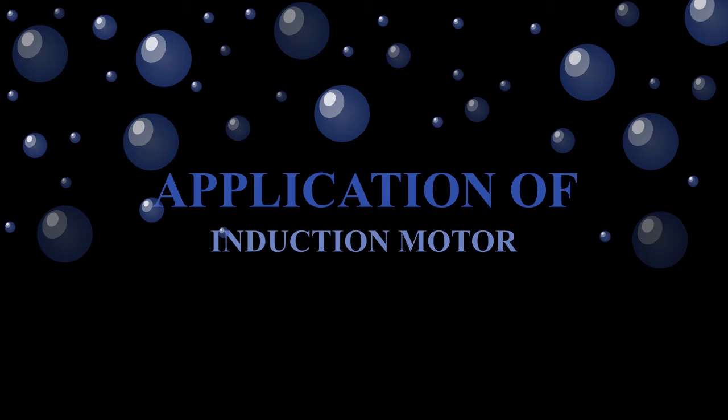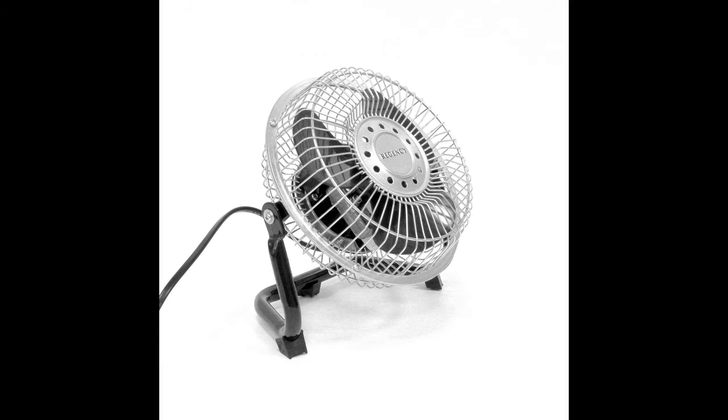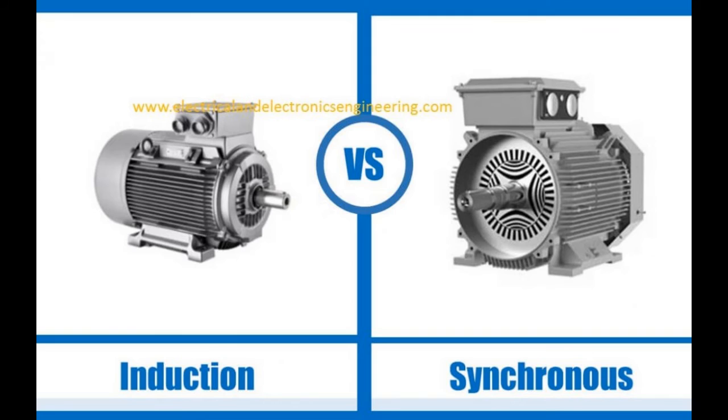I'm going to explain an example of the application of an induction motor. We mostly use induction motors in fans, domestically and industrially. Why don't we use a synchronous motor rather than an induction motor? A synchronous motor isn't very practical domestically or industrially because it needs a complex starting and closing strategy, and it is very heavy in size. Not only that, we can't obtain variable speed using a synchronous motor, but with an induction motor, by changing the frequency of the AC supply or the number of coils, we are able to use variable speed for the fan.